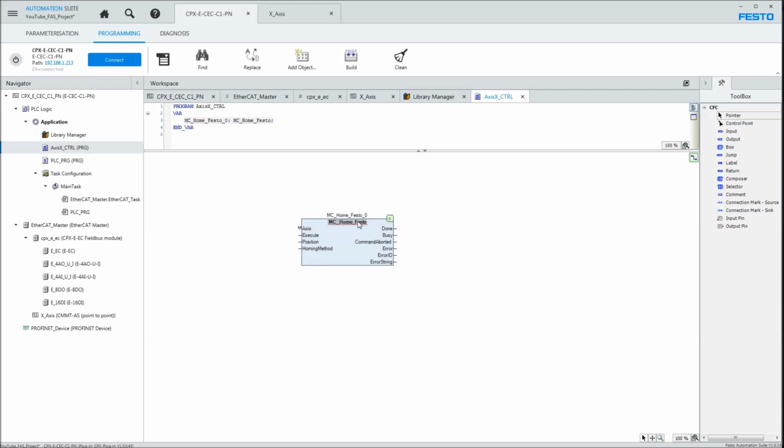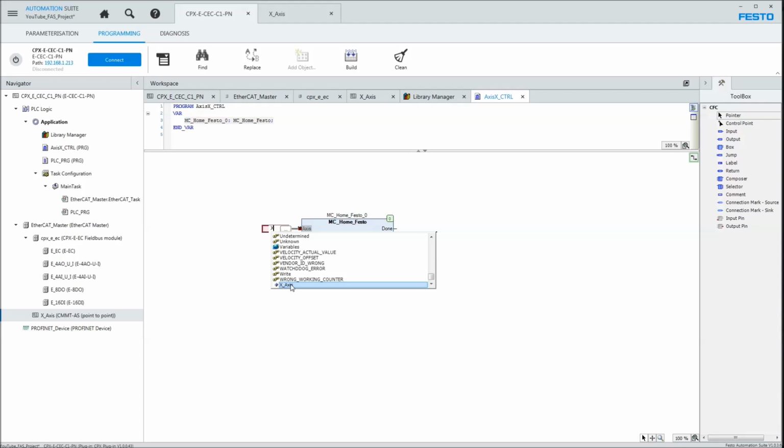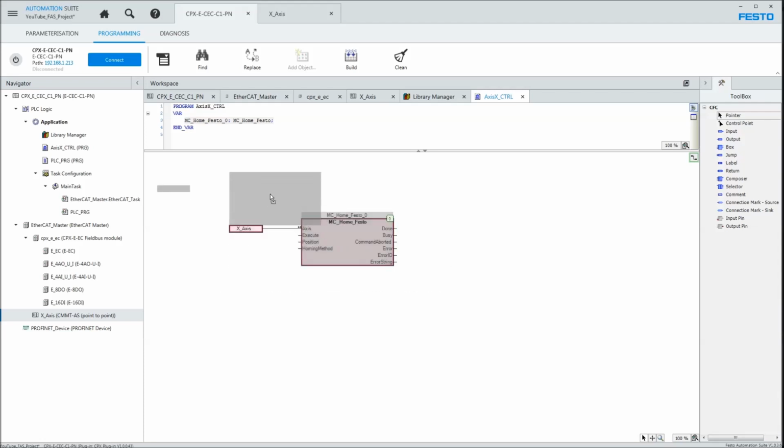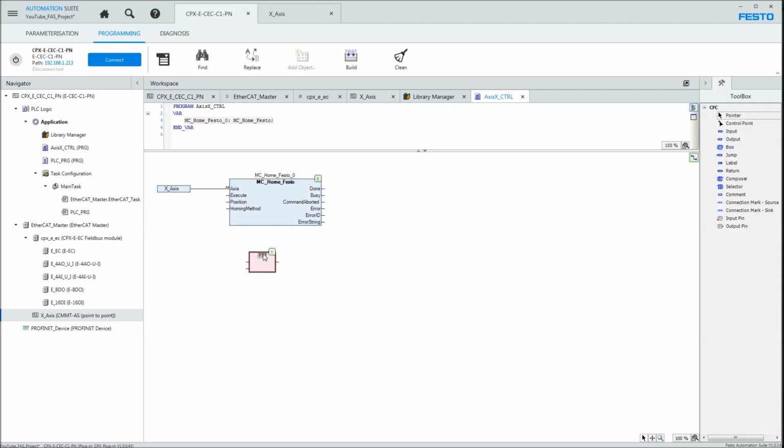It's underscore red because you're not finished configuring the block. That's because this axis here needs to be configured. What you connect to this axis here is the name of this. So if you click here on the red dot, just start typing X axis, and you'll see it comes up with the drop down. Double click, hit enter, and now we have a block that's all good. You can click this, drag it all up there, and simply come over here and continue to add the blocks.